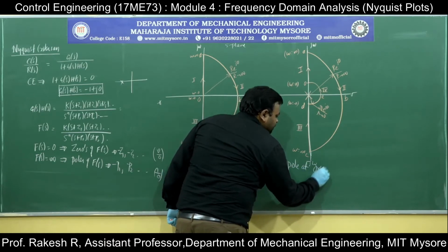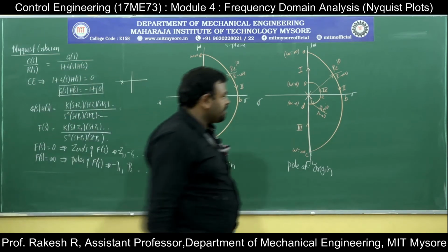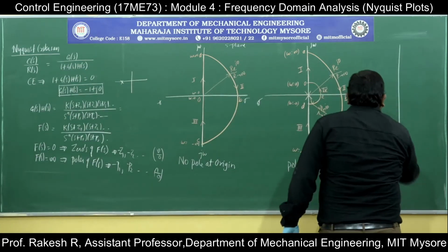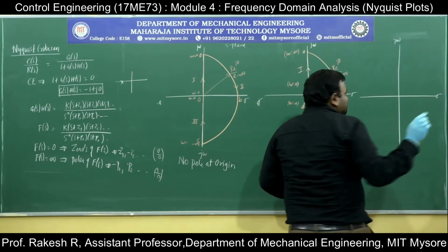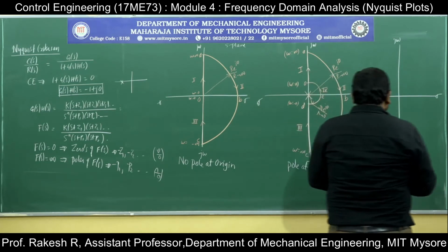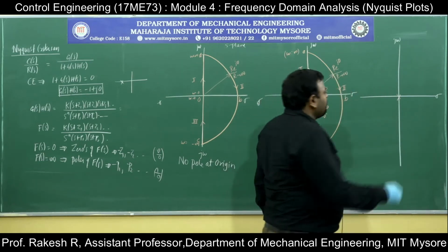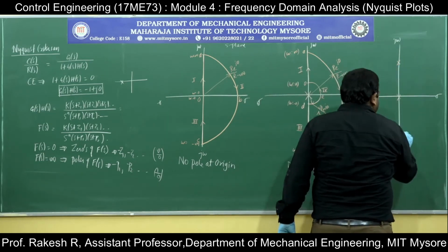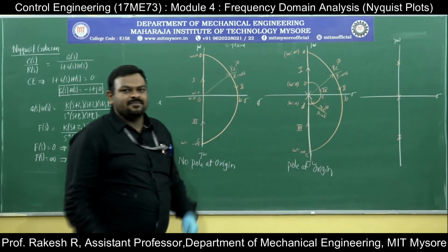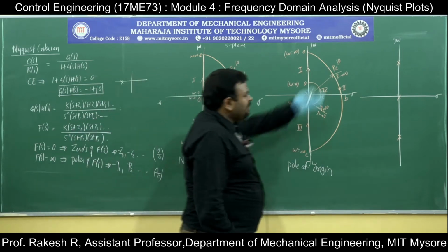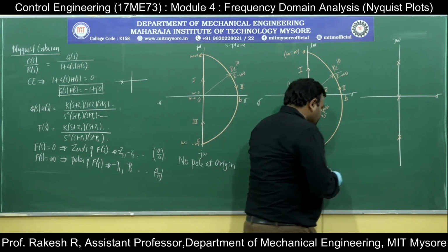Again a small value. This is the case of a pole at the origin. Most of the cases will be like this. Then another case is there. What does that case mean? Again sigma, j omega. This is all the S plane cases. Here there is a pole, but there is a complex pole on the imaginary axis. Complex poles are obtained in pairs, plus or minus, as you already know. So plus will be there, minus will be there. Pole at the origin as well as complex poles.